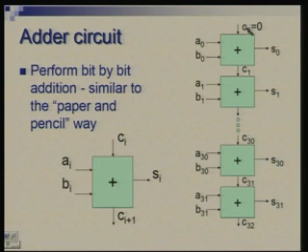Initial value of course is 0, which is the initial carry for bit number 0. I am assuming that bit 0 is the least significant bit and bit 31 is the most significant bit. Now, following 2's complement notation, I do not need to worry whether A and B are signed or unsigned numbers, whichever they are, I simply pass them through a circuit like this, which to begin with is designed for unsigned numbers.